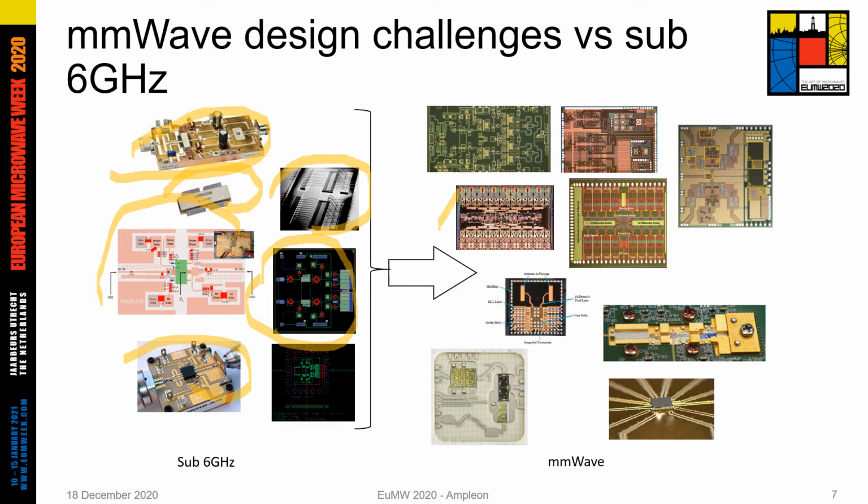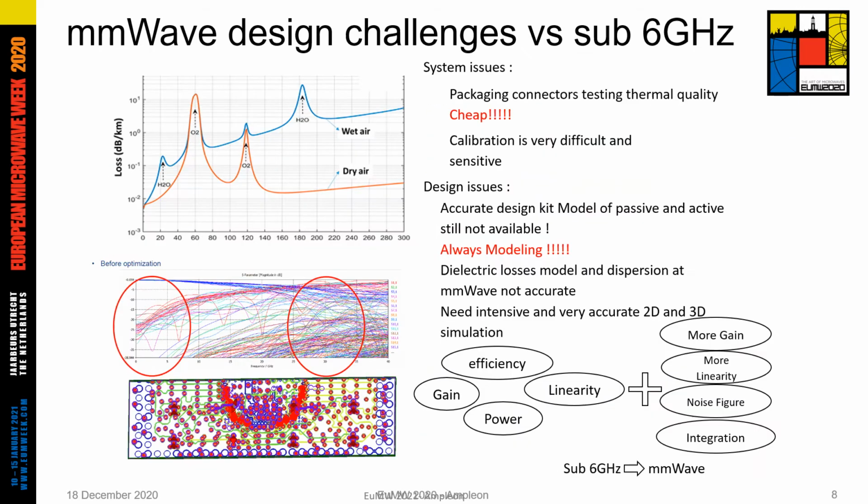You see these multi-channel solutions, analog front ends. Higher integration level means that there is LNA, PA, vector modulator, or sometimes even the switches integrated, or power dividers, and even mixers. And also the packages are smaller, like ball grid array package or QFN, but high frequency LTCC packaging as well is deployed in the millimeter wave. This shows the clear difference between millimeter wave and sub-6.